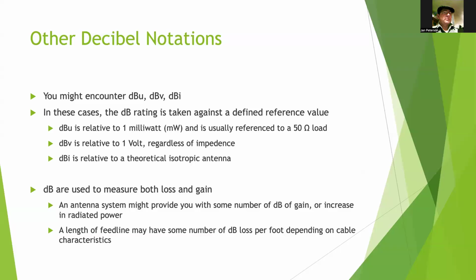So if you ever worked with cable TV, that is 75 ohms. So it's different from the radio frequency stuff that we use. Okay. So if you've got a hunk of old cable TV coax, don't use that for your ham radio antenna because it's the wrong impedance on that cable.